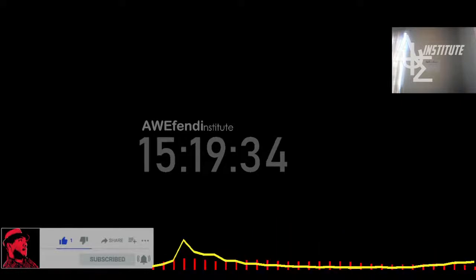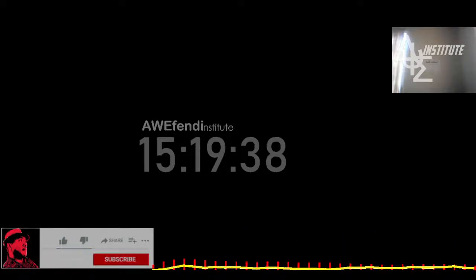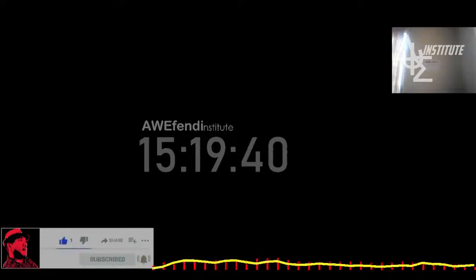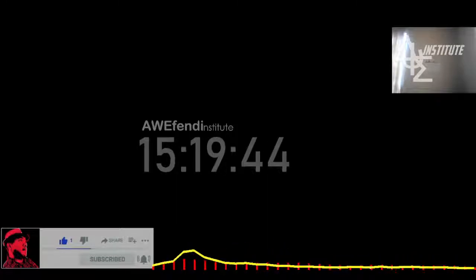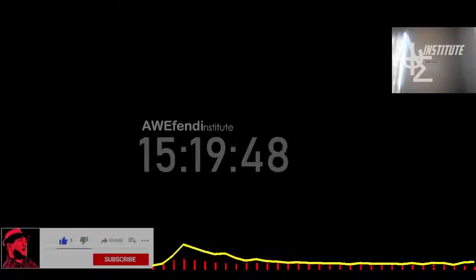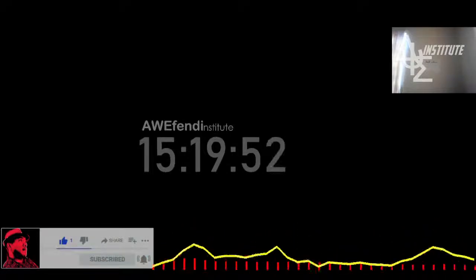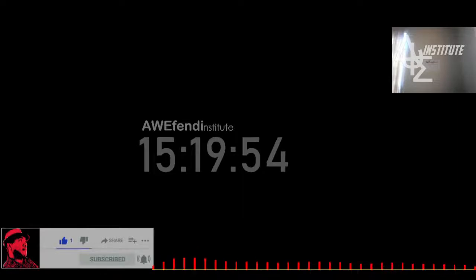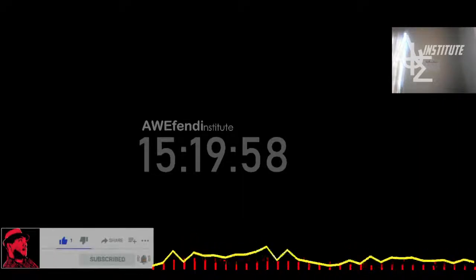Let me do these little weightless particles that are showing the fluid flow. Here you can see the first design, of course, no real obstacles between inlet and outlet. It's letting the flow pretty much do what it wants to do. And we have a big recirculation zone here, so that's probably not the best design. I'm going to activate now the first rib design. This is actually the one that we had in the previous CHT calculation.